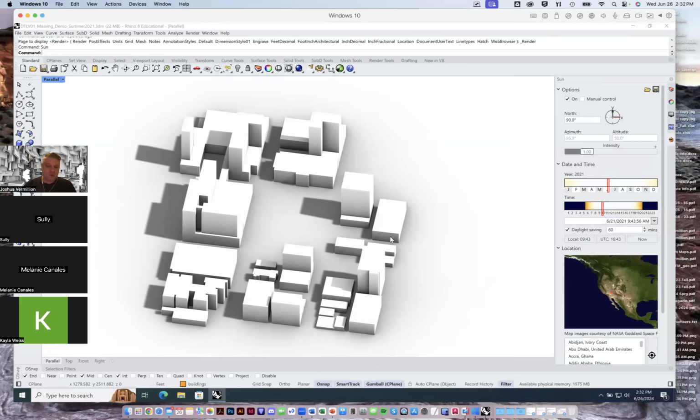I mean, to me, I think the important thing is I just showed you that there are certain tools, if you want to get a little more granular than what Revit shows you, you could actually do them, and I'll make them accessible to you guys. However, I would just say that you have a similar set of tools in Revit. They're much easier to use. We've already started to use them. Just use them in Revit as you go, and I think you'll have a much easier time. So if you want to do some sun path diagrams, definitely give that a try in Revit. You know how to do it. You set it up in Revit, turn it on, set it to the time that you want, and then you can export it out as a JPEG or a PNG, right?